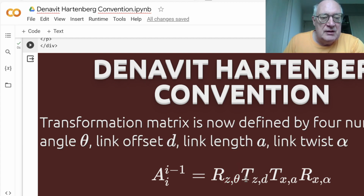Then followed by translation along z by distance d. If we have a linear actuator, then this would be our actuation. Then this part here would be fixed, theta would be constant, and d would be a variable. If you have a servo motor, theta is a variable and d is a constant. So we translate along z by distance d, then we translate along x by distance a, and then we rotate around x by an angle alpha.